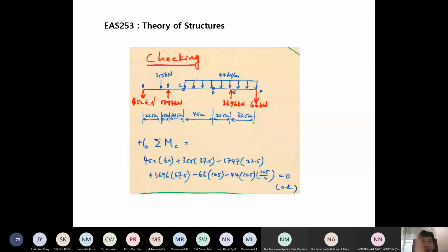The difference between case 1 and case 2 is that in case 2, we cannot find a free body diagram where you can write down equilibrium equations and solve one of the unknown forces directly. We cannot. We have to solve simultaneous equations for this particular case 2. That is the difference. But the rest, the principle, use equilibrium equations, cut at the hinges, form equilibrium equations at the hinges, they are all the same.